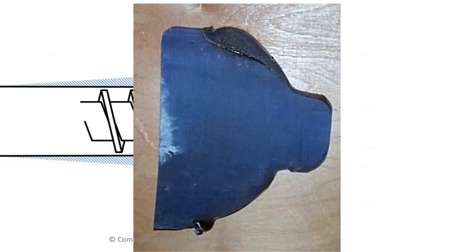We can see here the discoloration and the burning of the material. This is PVC, and PVC will show you where the shear stresses are very low because it'll start to degrade. And it's like a cancer. It'll just grow and grow and grow and ultimately get picked off and may appear in your product.